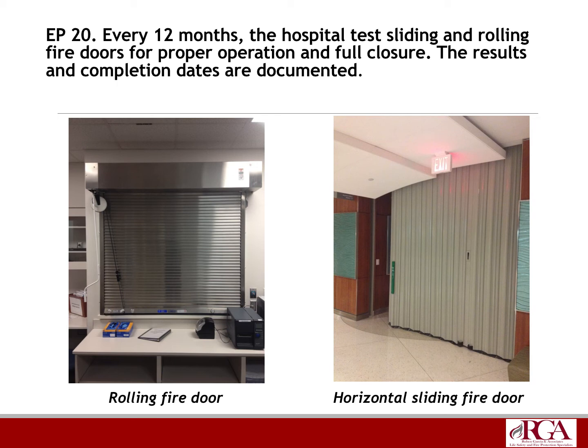Now, you might have a shutter or a rolling door that's not a fire shutter. It may be for convenience. There's a difference, but they're going to be stamped. You're going to see the fire rating labels. These have to be checked thoroughly per NFPA 80. There's a checklist criteria. Get your overhead door vendor, whoever does these type of doors, to get out and service these and get a formal once a year inspection performed.